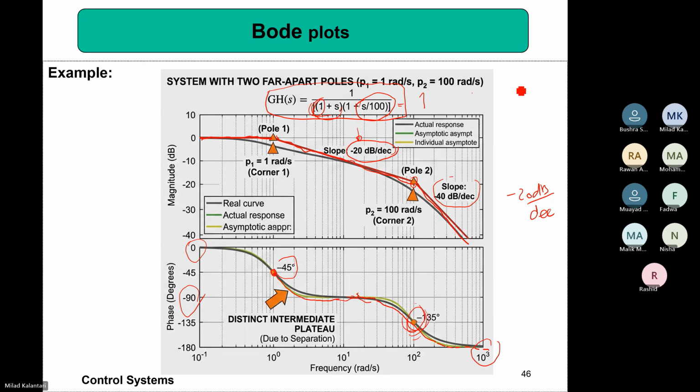Why? Because at high frequency, you may simplify this with just s squared, second order. You just ignore the other terms, the lower order terms, since the frequency is high. This term should be dominant. And then if you put in j omega, it will be negative omega squared. So it goes to 180 degrees, right? But in this transition, sometimes is important for us.